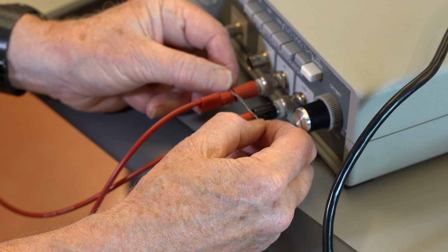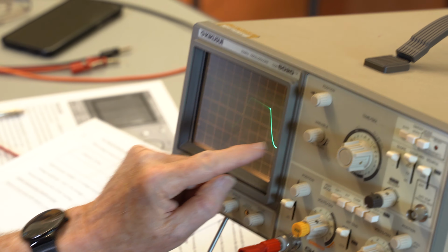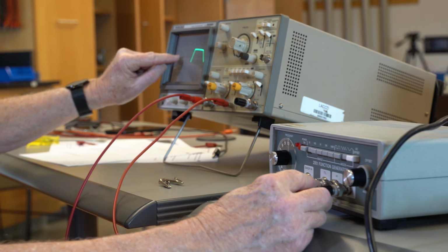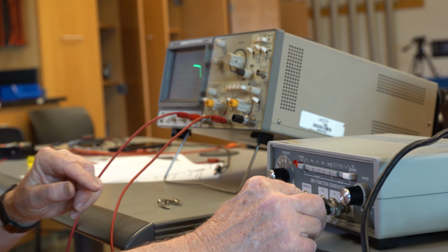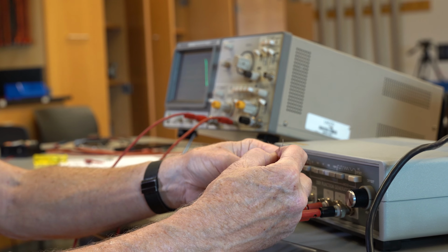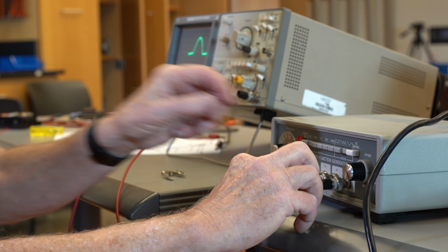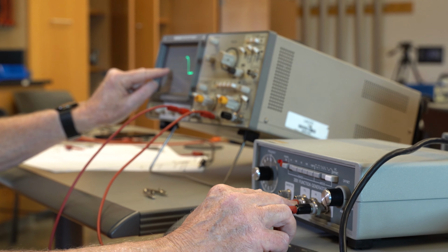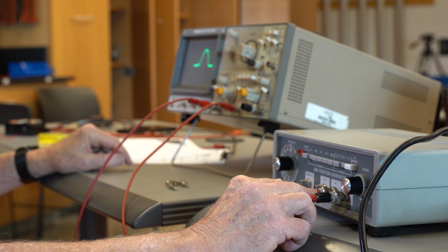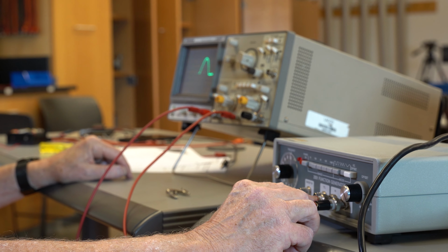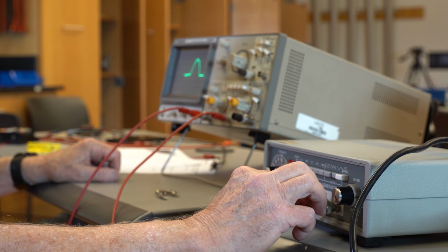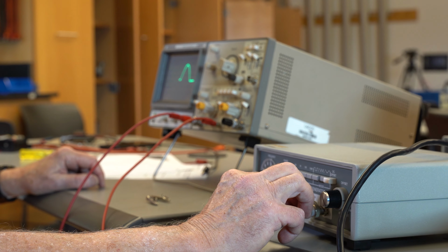So what we do is touch it there, and you can see the top form of this wave has been shorted out or cut out by the diode, because the diode only lets the current flow one way, not the other way. If I turn the diode around the other direction, you can see now the bottom of the wave has been cut off. Current can only flow positive, it can't flow negative. The diode is a really useful device for converting AC current to DC current. You can put it together with other diodes to make it more efficient.